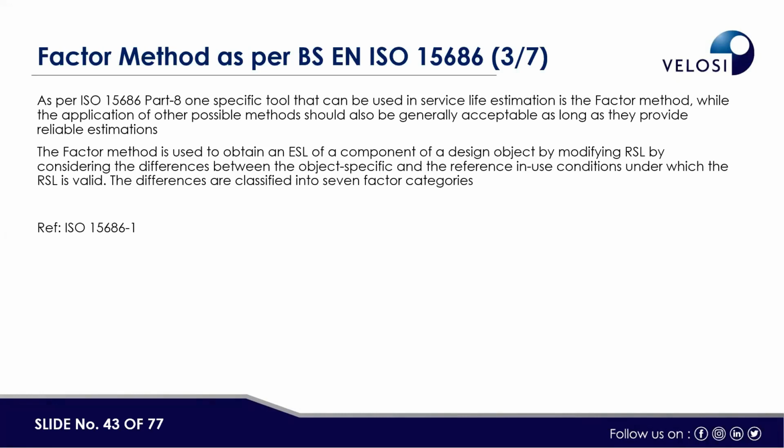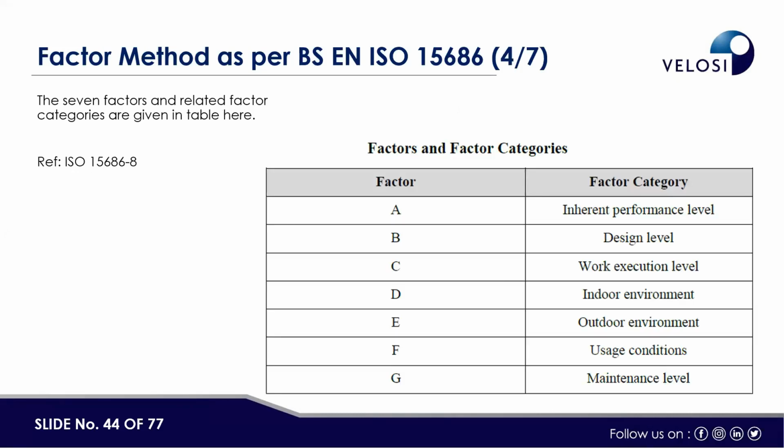In Life-365, we will get to know how exactly, once the concrete is put into use, the chemicals are degrading the concrete and how the service life is coming down. But the factor method is generally a semi-qualitative method, we can say. Now, there are A to G types of factors that have been categorized based on this code.